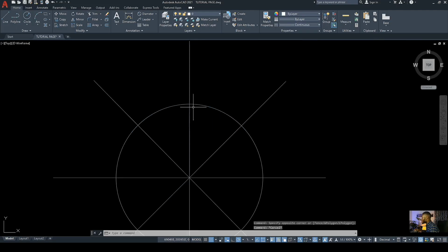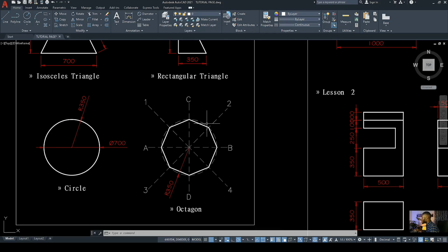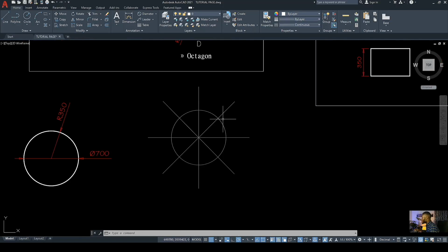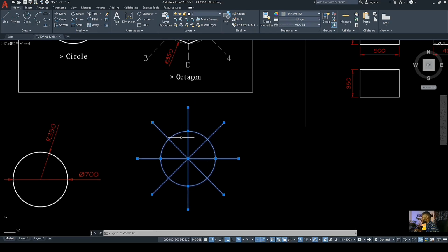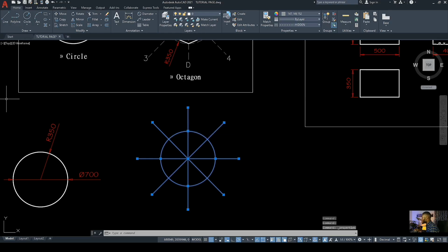One thing you observe is that this line is showing broken, showing that yes, it's a hidden line. But if we come to this line, it's not showing that. So that moves us into further editing of the property of our lines. You just click and select the whole lines, then right click, then go to property this time around. Let's see, you select them, then property. Okay, my property fell on my extended screen.